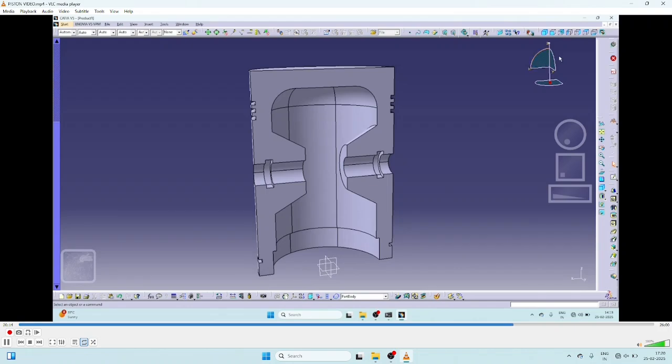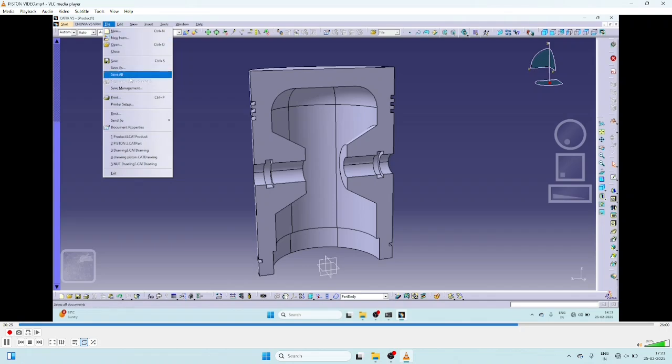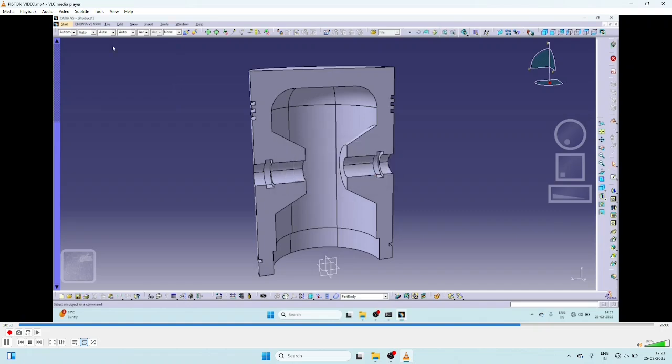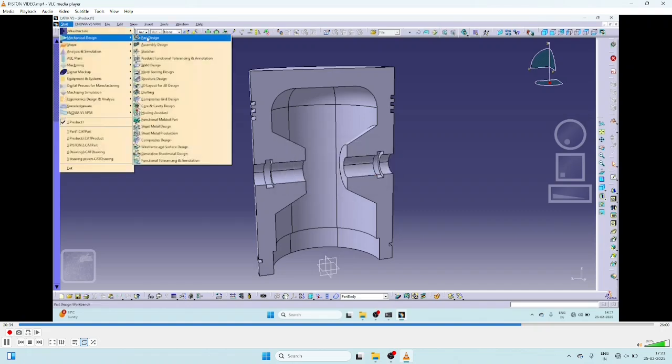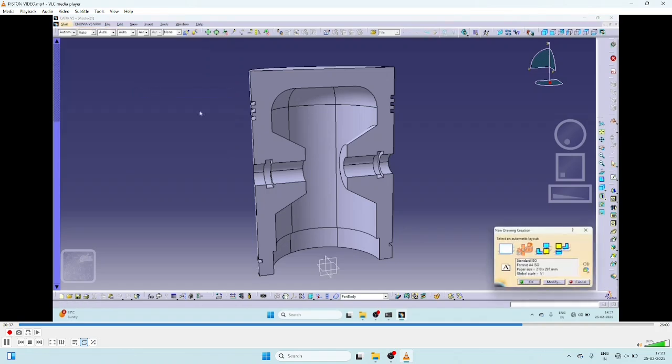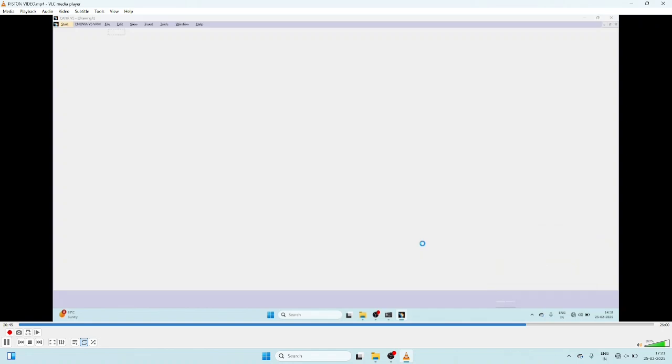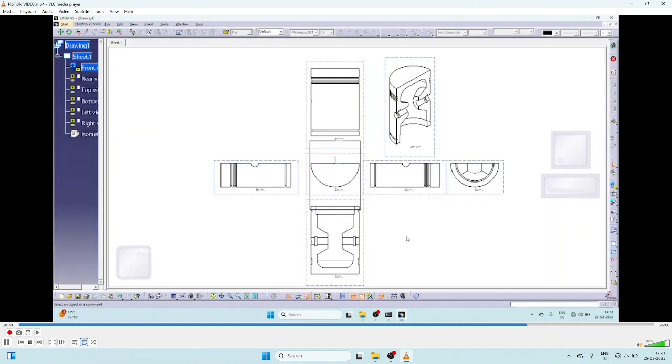You can save this file. First save, and then okay. Now to make the drafting, open the drafting tool, modify, select portrait. Okay, now automatically it generates the drawings. So it is better to delete unwanted drawings because space is very much limited.